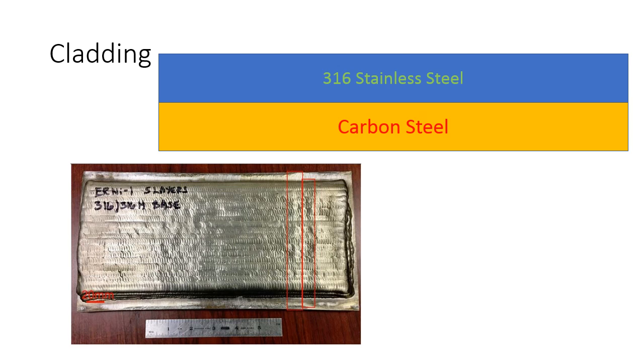I don't know where you would use this, but in oil and gas, a lot of times they'll clad carbon steel valves because they're cheap with a stainless steel or an Inconel or a Hastelloy, these nickel-based alloys, because to get that valve made in one of those alloys or materials would just be super cost prohibitive.